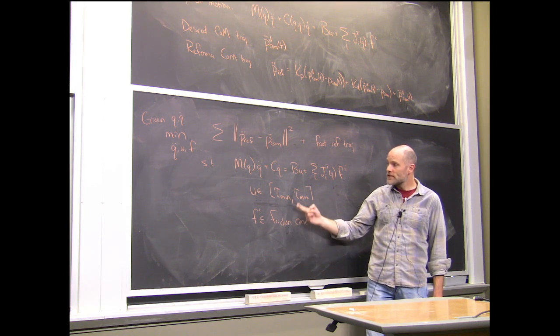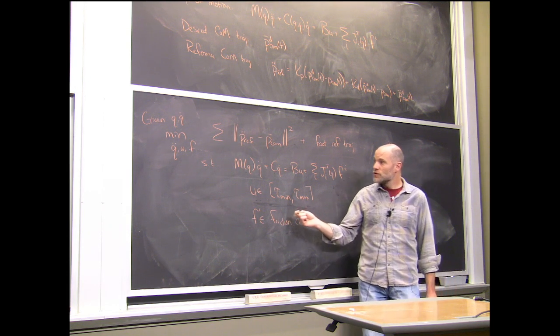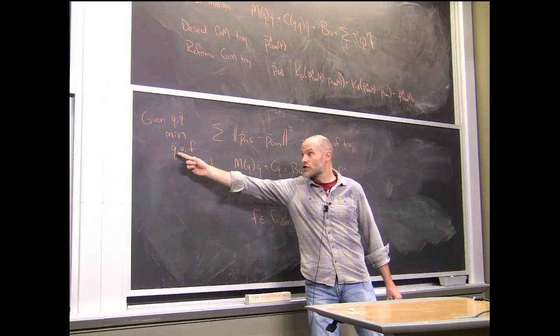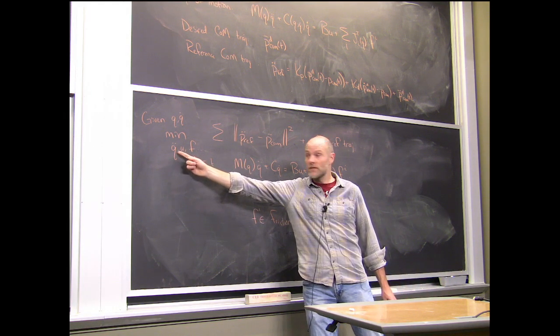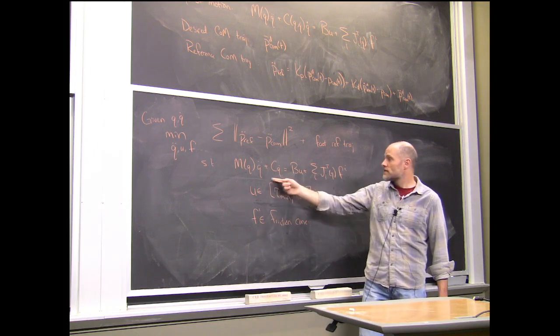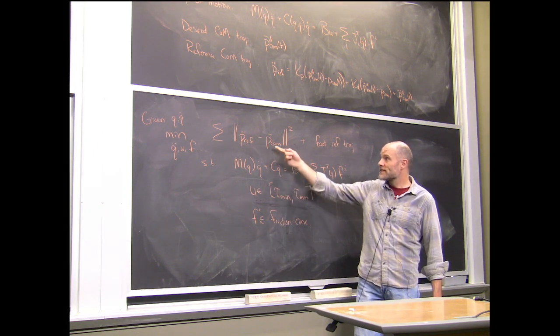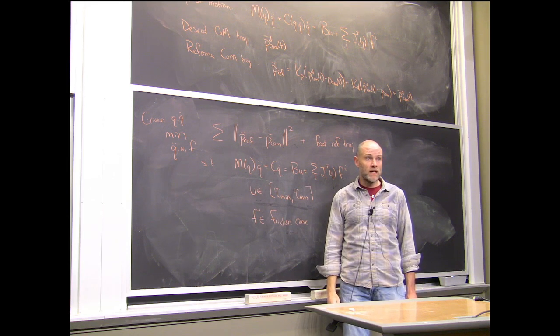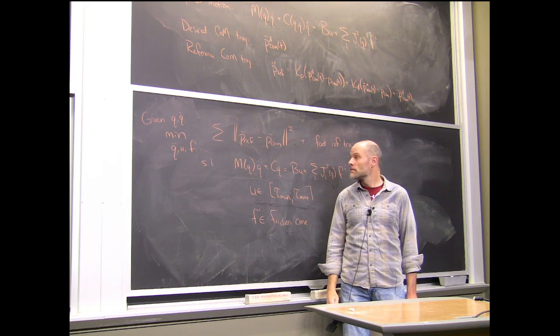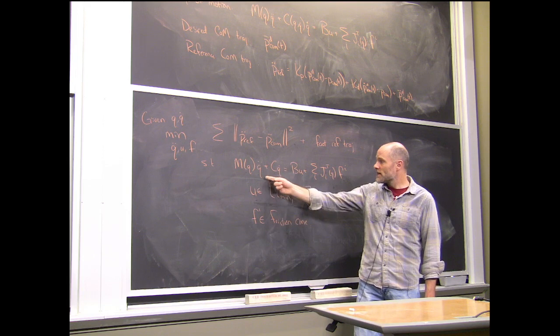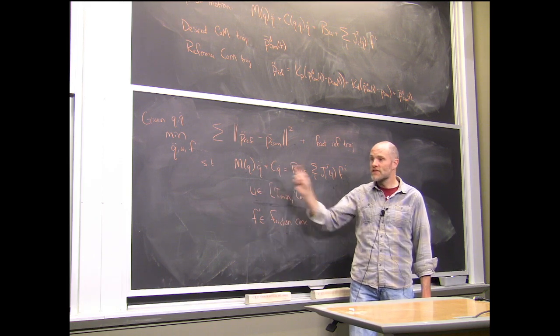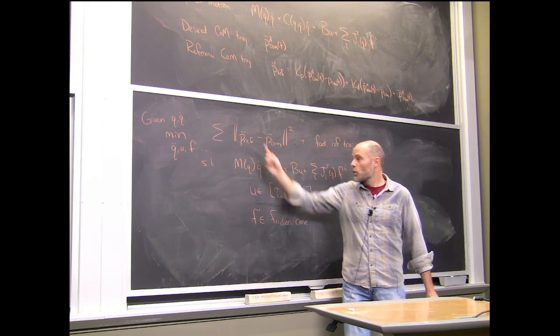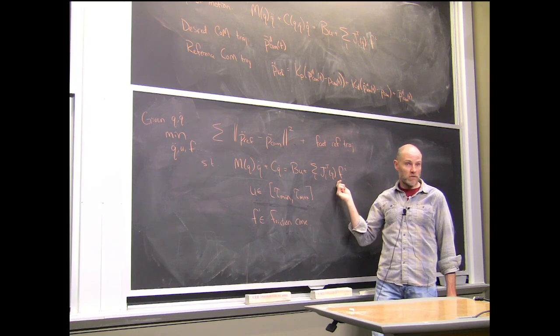Okay, so instantaneously, I'm going to choose the Q double dots, these joint angle accelerations, such that given the dynamics, my center of mass dynamics is as close as possible to my reference center of mass dynamics. And this is simple because in the one-step case, this is not looking ahead into the future. In the one-step case, this is a convex optimization.